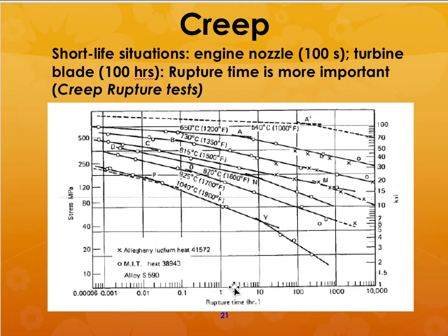So you can see that if you go very close to that line, then your lifetime will decrease drastically. And so 1040 degrees centigrade might be very close to the melting point of the alloy. So that's why you have hardly any time left before the component will fail.